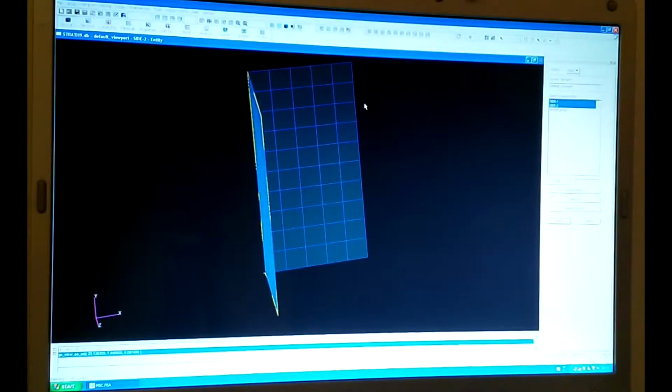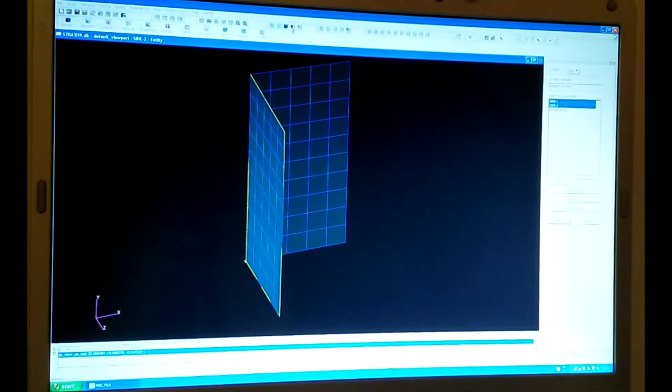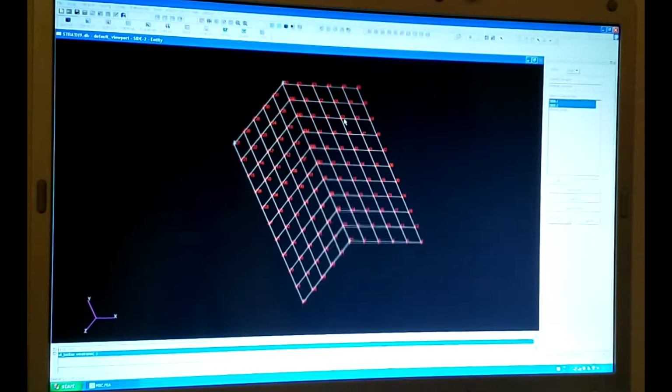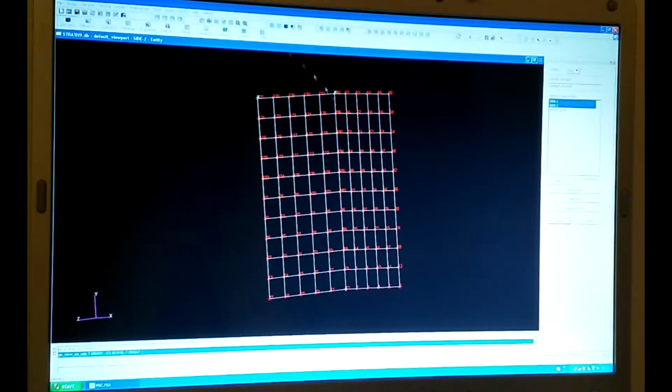When you're completed meshing all the panels and done the verification, post all groups of elements and rotate to visually inspect that you have all the panels of the stowage unit meshed and in the correct position and orientation.